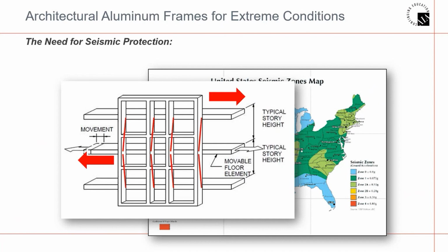As the building shakes back and forth, the middle floor is shifting to the left, while the floors above and below are shifting to the right. A typical curtain wall is mounted to the exterior of the structure and anchored back to each floor line as it passes it. As the floors drift back and forth, the anchors of the curtain wall pull the frames with them. The glass in the frames is dead loaded on the horizontal and tends to sit still. As the verticals begin to tip back and forth, glass moves with the horizontals.